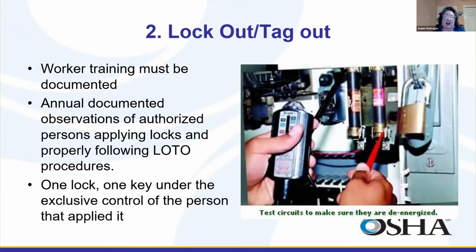Okay. And just realize that each person involved in the lockout tagout has to apply their own lock and their own tag and keep the key in their pocket. So if you have a lockout that involves 4 people, there should be 4 locks and 4 keys, and each one has control of their key. Okay, so